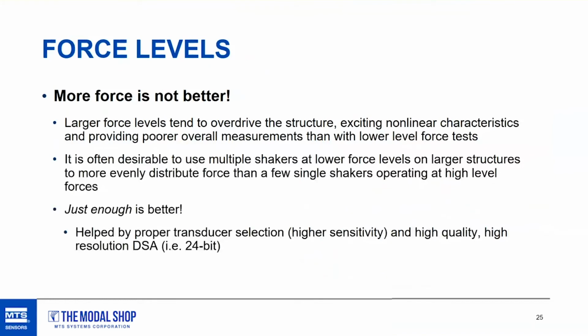Another question about force levels. When it comes to experimental modal analysis, no, more force is not better. Basically with modal analysis, the assumption we make is that we're talking about linear structures and linear test levels.